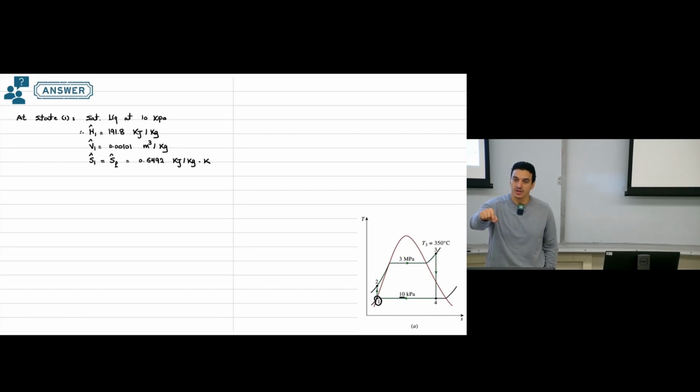So now, since we understand the steps, we know what information we need at this point. We need the enthalpy H1. This is enough, but we need to find H2, H3, H4 in order to find these other enthalpy values. This is why we have the specific volume. This is why also we find enthalpy at this point.